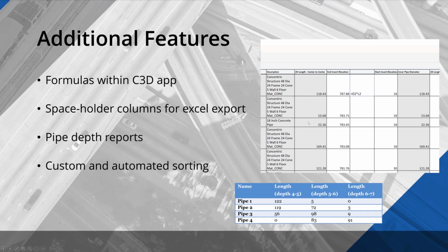How this stuff sorts, you're going to have detailed control on that, like just sorting by the header, ascending or descending, or you can manually sort different rows and columns however you see fit. And then all of that again can be saved out to a template. It's going to support drainage areas, right? So as you sketch out or create drainage areas for those different catch basins, that information can be pulled in as well and brought into your analyses.